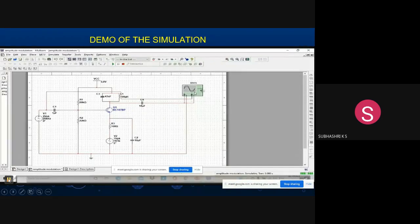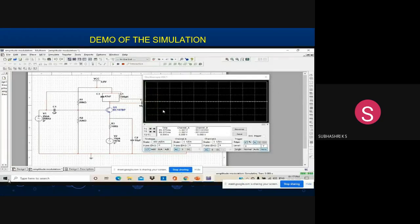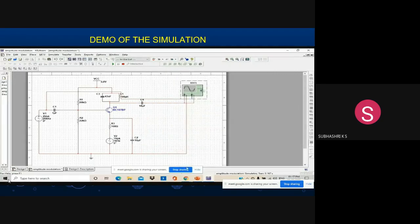The resistors R1 and R2 are used to form a voltage divider biasing. The capacitor C3 and the inductor L1 form the tuned circuit. The AC source V1 is used as a carrier signal and V2 is used as a message or the baseband signal. We have set the message signal as 1 volt peak to peak and 1 kilohertz and the carrier signal as 2 volt peak to peak and 25 kilohertz.